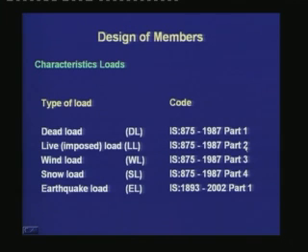There is a subtle difference between live load and imposed load: if a part of dead load does not act throughout the life of the member, if it acts only at certain periods, then that part of the dead load can also be included as imposed load. It is up to the discretion of the analyst to consider whether a fraction of dead load is imposed or not.